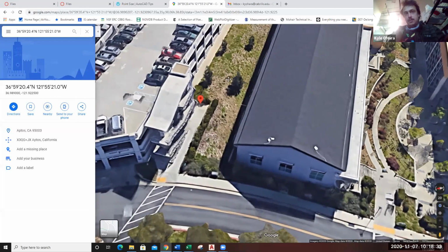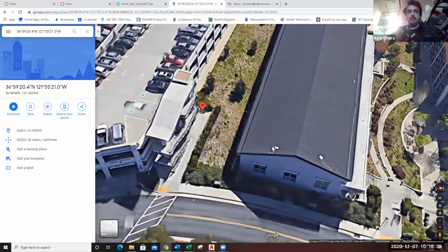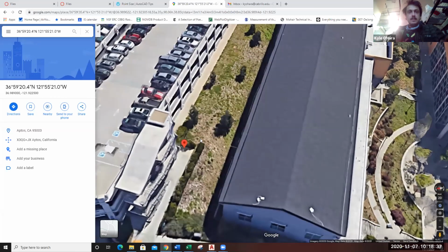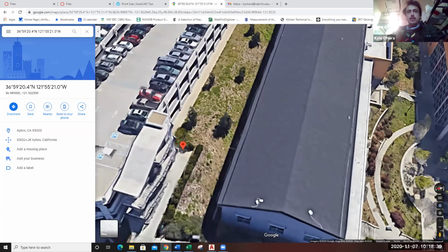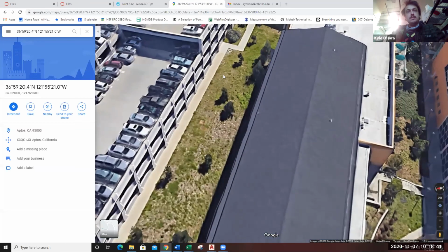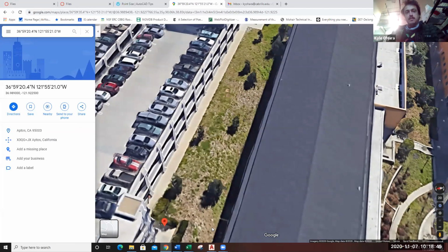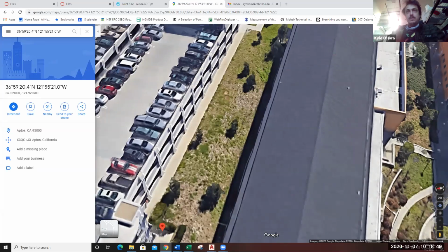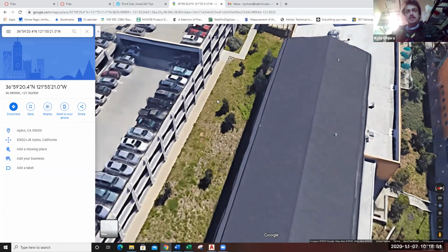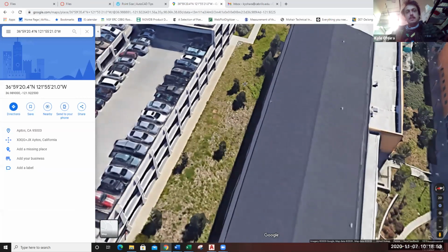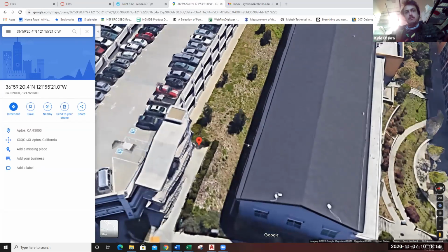Now, a couple other features about this zone. It's pretty narrow and long. So we're going to expect all of our angular measurements to be pretty narrow, right? If we're surveying this length, our horizontal measurements are kind of constrained by the Health and Wellness building on, was it south?